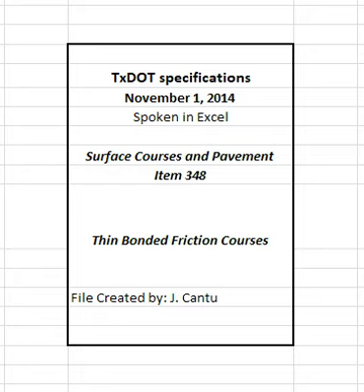Use the procedures described in Tex-233-F, when directed, to plot the results of all production and placement testing. Update the control charts as soon as test results for each sublot become available. Make the control charts readily accessible at the field laboratory. The engineer may suspend production for failure to update control charts.